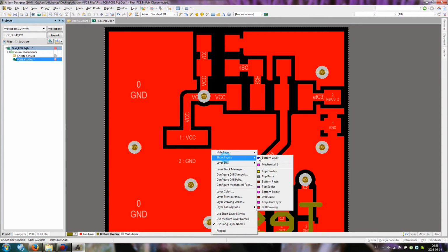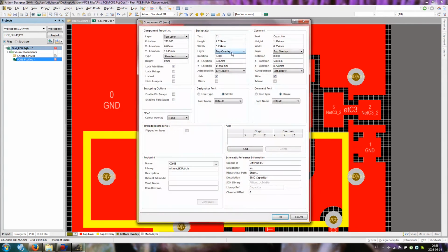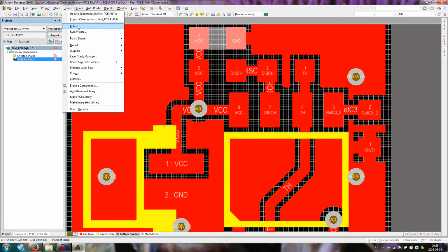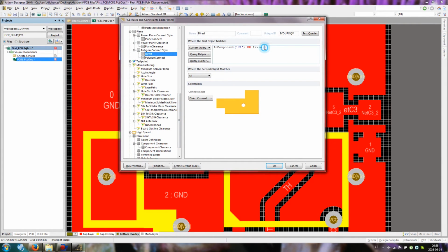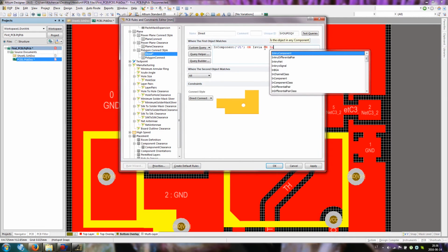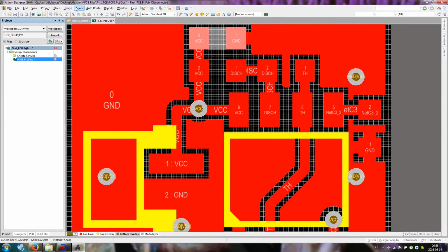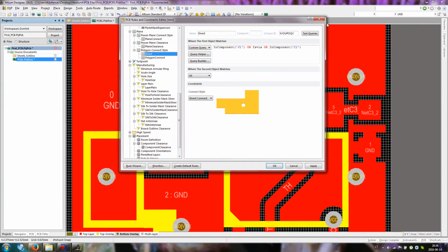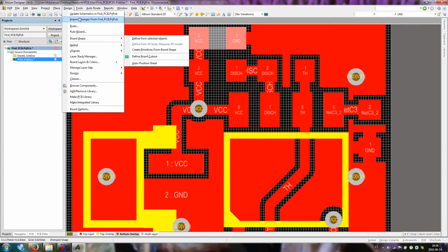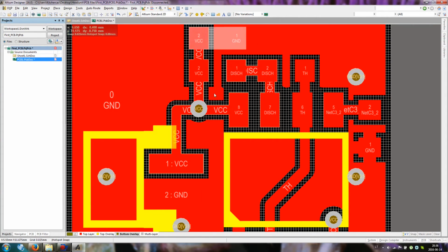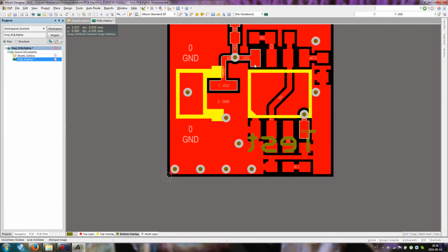And of course, let's add it like C1. Also make it for C1 rules, or in component C1. Okay. Design rule, and not rules. Repour design. Repour all. And as you can see now, this component is also connected.